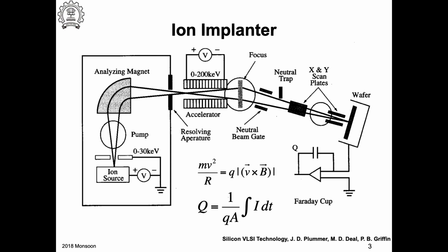Now it's very important to construct what is called a profile. It is very clear that the ions would not sit at well-defined depths. You are implanting a very large number of ions, so it is possible for us to talk about the distribution of the ions, and what the average depth is, and what the spread of this distribution is. So what you see here again is TRIM simulations of 99,999 ions of boron implanted into silicon at 100 kiloelectron volts.